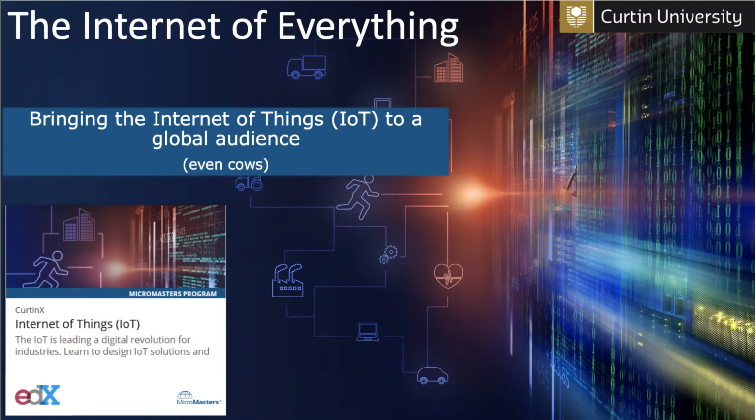Because later on, to be honest, for the prototype platform I would always choose something that's cheap and has as many GPIO pins as possible, because then I can connect a bunch of different sorts of sensors to it. Then later on, if I wanted to make that an actual product, I would go and build my own PCB for that product and implement everything on the same board, and that's where I can be more specific and more, I guess, stingy with what microcontroller and what platform I'm going to use. Otherwise, as a prototype, anything that you have experience with, whether it's a Raspberry Pi, ESP32, or Arduino, all of those would be a good choice. I hope that answers your question.